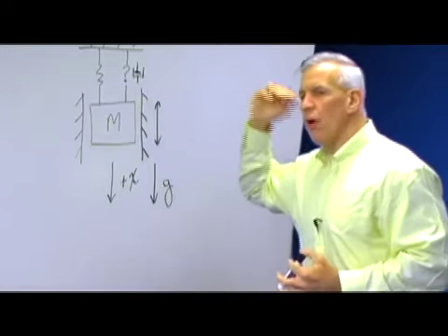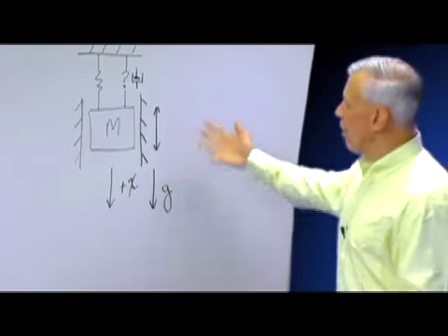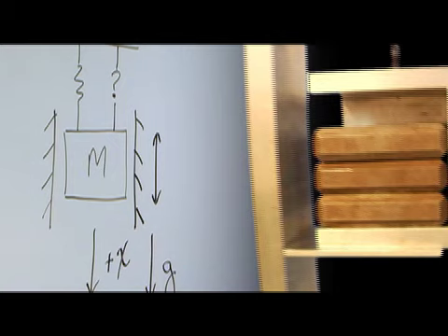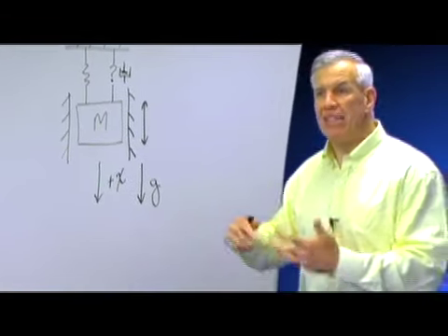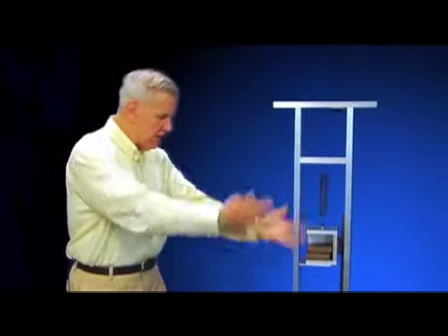And so this is also a pure and ideal element because in addition to being pure, only having friction, I also assume that it's linear in behavior and that the force applied to it is proportional to the velocity of its ends. Linear, just like the spring. So this then represents my physical model based on simplifying assumptions, judgment, and experience applied to my dynamic physical mechanical system.